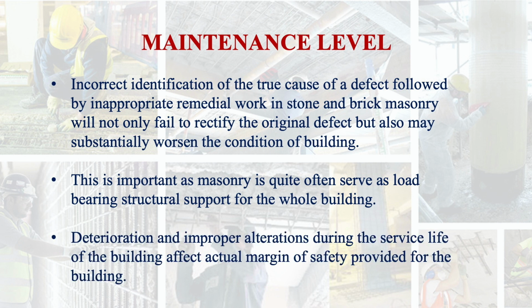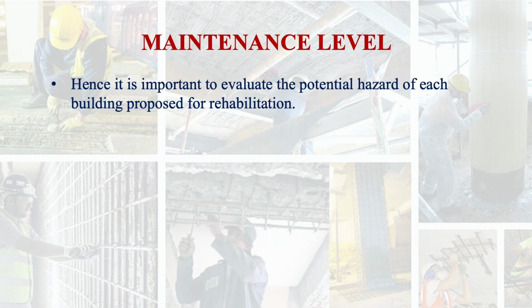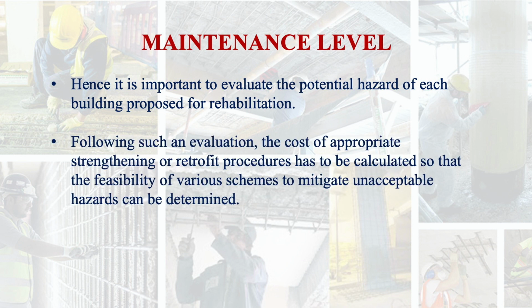Deterioration and improper alterations during the service life of the building affect the actual margin of safety provided for the building. Hence, it is important to evaluate the potential hazard of each building proposed for rehabilitation. Following such an evaluation, the cost of appropriate strengthening or retrofit procedures has to be calculated so that the feasibility of various schemes to mitigate unacceptable hazards can be determined.